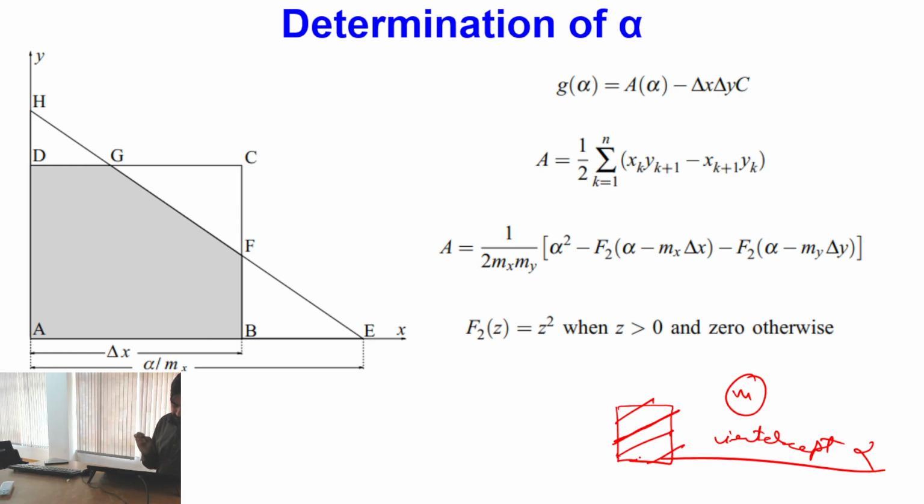So typically, consider this is one cell and this was the interface. When the interface is represented by a polyline using PLIC based reconstruction, I will get some straight line segment. This straight line segment will divide this cell into a polygon. Is this point clear?